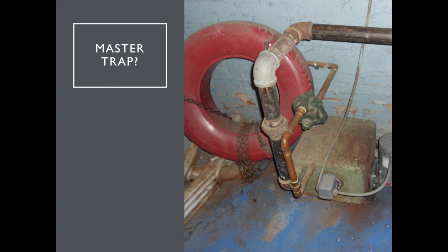Okay. And Jose is asking, does low water blowdown need to be done weekly on a system that is closed loop, or can this wait a bit longer? Typically, if it's a hydronic boiler, you'll have to check with the manufacturer. I like to tell them to do it once a month. If it's a hydronic boiler with a float, you almost have to get in and work the linkage up and down with a small screwdriver to make sure it works.